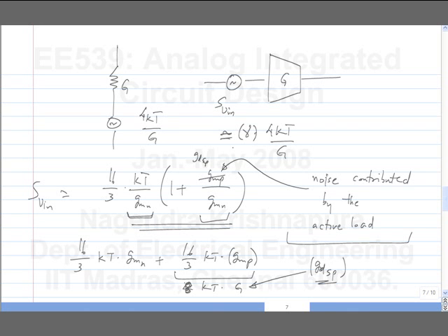So the only time when you have a better deal using a high resistance is when you have somehow an inherent current source. Normally we have voltage sources, and we convert them to current. If you convert to current using a high impedance, you will have a smaller signal current also. Maybe you have a smaller noise, but you also have a smaller signal current. Overall, you are worse off doing that. But if you have an inherent current source, like for instance the photodiode, you will have to make some of the impedances in the circuit very high to get a high signal to noise ratio.